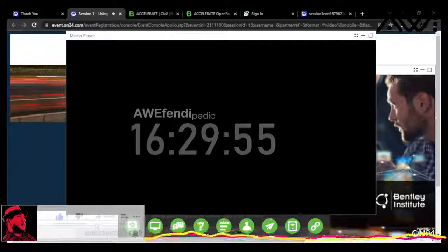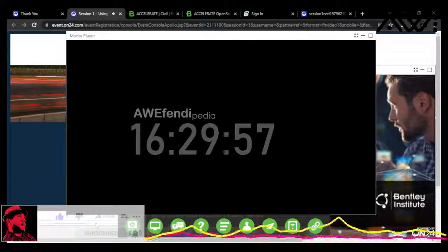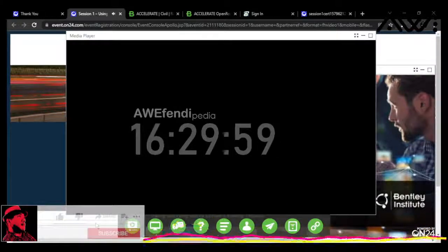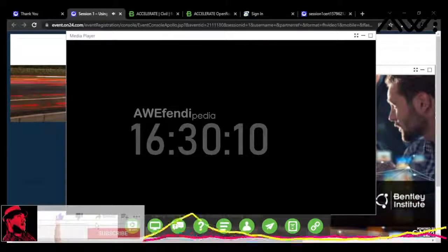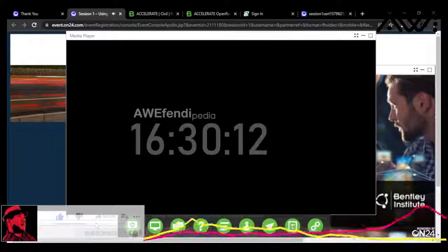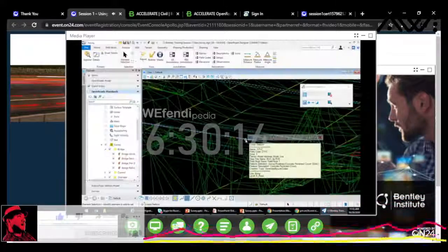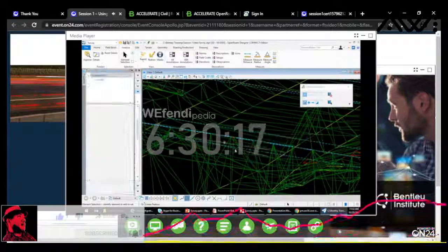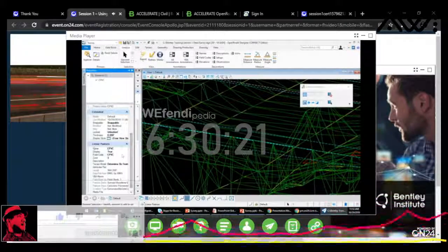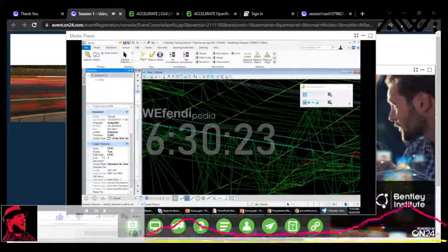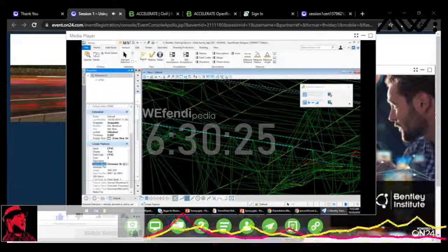So I'm going to click on this one feature and go to properties for it. Instead of changing all the feature definitions, all of the lines that have that feature definition, I just want this one not to triangulate to. So you can see I had to expand. I couldn't remember which category that was in. It's in the linear feature category, and I'm going to change just for this one crown feature.